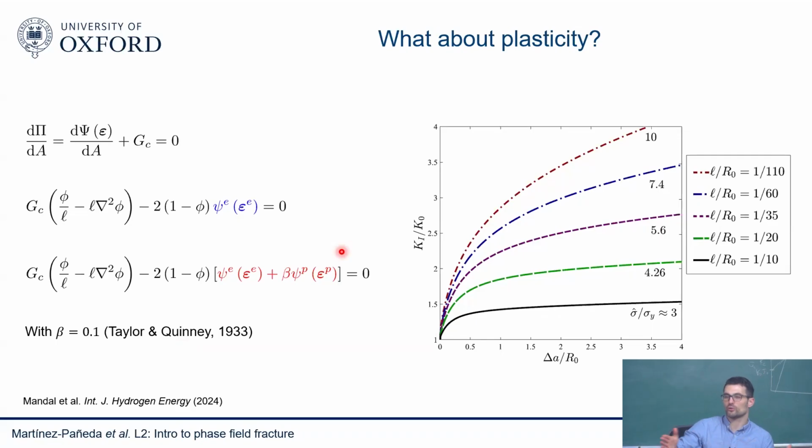If you vary the conditions, either by changing the strain rate or the load, you may have to think of another parameter to put in there. It might be that whether you put here 10% or 50%, it doesn't matter for your problem. But if you're interested, for example, in this kind of behavior, subcritical crack growth, where you get different R-curves, it can play a role.